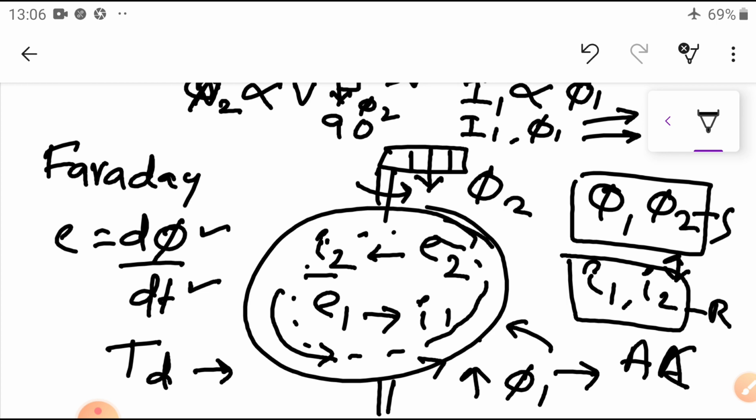Okay, so this is the basic principle. So how is that deflecting torque produced? The flux produced by the shunt magnet and the series magnet produces eddy currents in the disc, and the disc currents also produce their own magnetic fields. So these fluxes and the main fluxes interact, thereby a torque is developed, since the disc acts as a rotor and phi 1 and phi 2 act as a stator. Then the deflecting torque tries to rotate the disc in one direction.